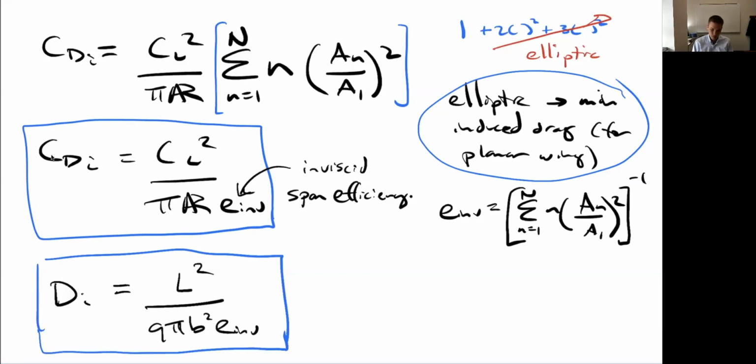We won't do that in the homework, but if you want to, we just plug these things in to this thing. And if you use a small angle approximation, for example, you would get something like this, that alpha minus alpha 0 is equal to 2b pi c. Again, we're not going to do this in the homework. We're going to use the vortex lattice method, which we'll discuss later, which is potentially a little bit more versatile. They each have some advantages, but it's certainly a commonly used approach.